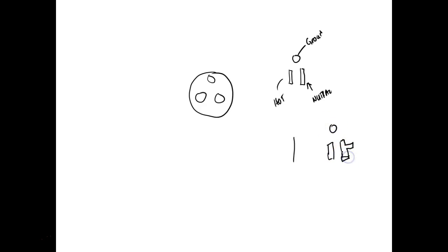This is also bigger. This is a 20 amp plug. And this right here is a 15 amp plug. If you look at all the plugs in this classroom, you'll see it's got the little notch. So a 20 amp device should have this T coming off of it, but a 15 amp, so I can run a 15 amp device in a 20 amp plug, but I can't run a 20 amp device in a 15 amp plug, because the 20 amp device is going to have this thing right here, right?